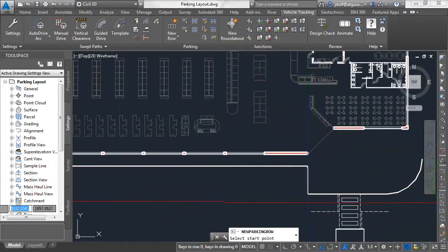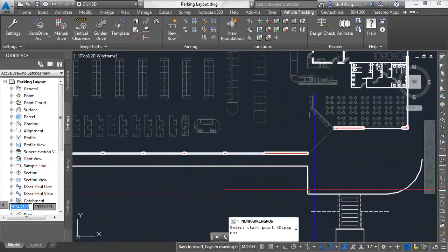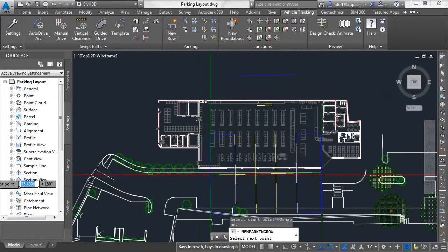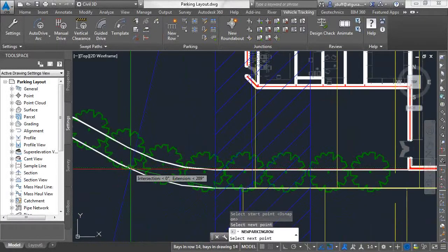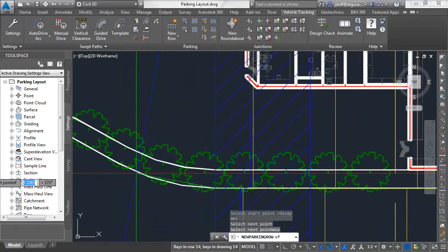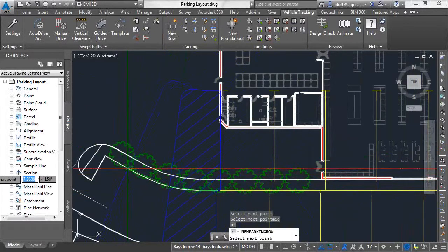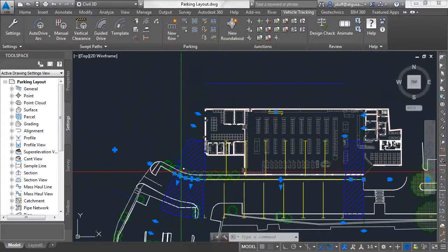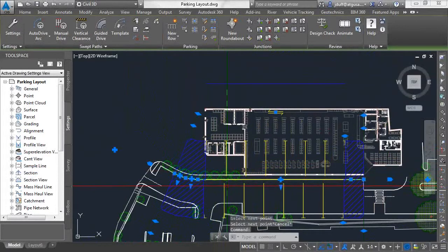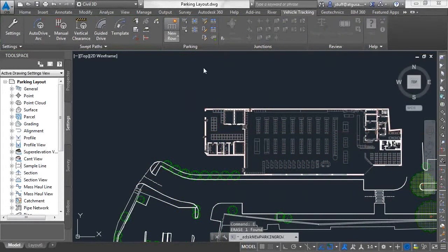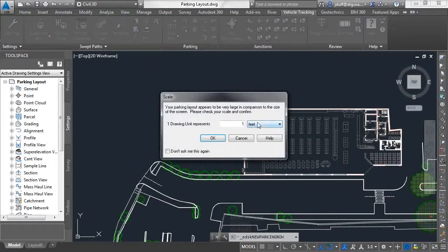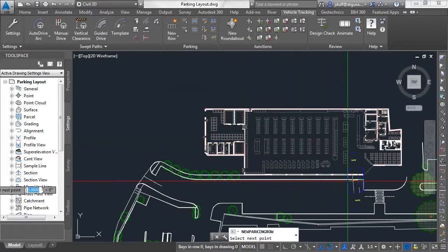Vehicle tracking is really easy. I just accepted all the defaults, and generally that's what you're going to do starting out. You just go in here and snap it to your line work right here. Kind of made those parking bays really huge. I was making them the size for the F350. Maybe my drawing is in meters. Let's try that.